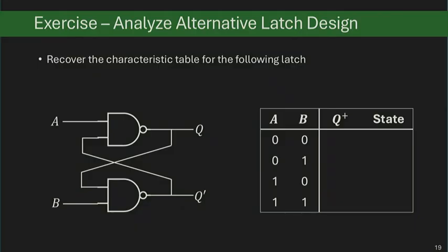Mark, do you need any help? Yeah. So you see, with any input value you put into the latch, you have to evaluate both Q and Q prime, because sometimes it could be an invalid case. Right, actually, with 0, 0, the first case you tried, 0 makes this a 1, 0 makes the bottom output a 1. So in that case, both Q and Q prime are 1s, which is not a valid scenario. Right? That's essentially like the 1, 1 case with the regular SR latch.